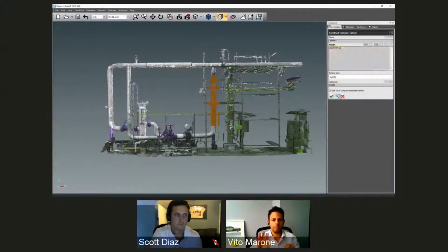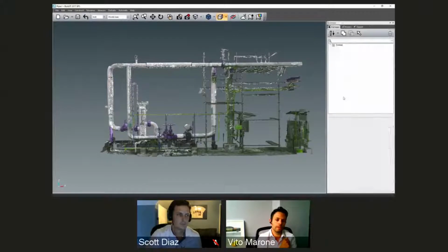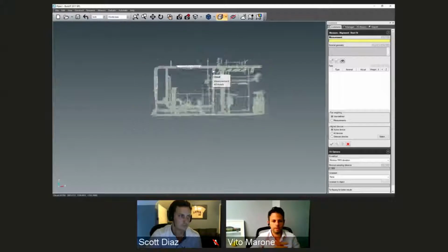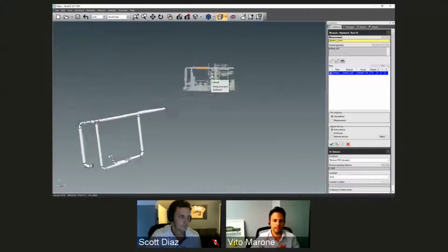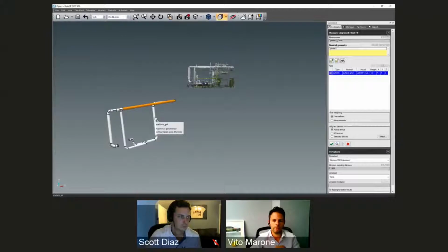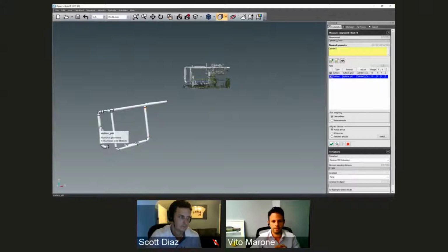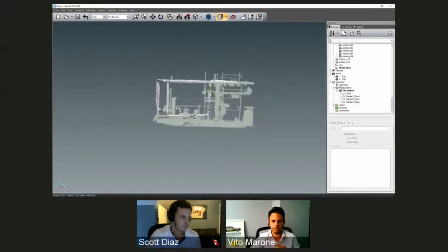We're going to do an alignment where we take 3 parts of the point cloud and associate them with the 3 parts of the CAD, which is another type of alignment in the software. Then you're going to see the point cloud overlaid on the CAD, and from there an analysis of the actual CAD to part, verifying that it's manufactured properly.